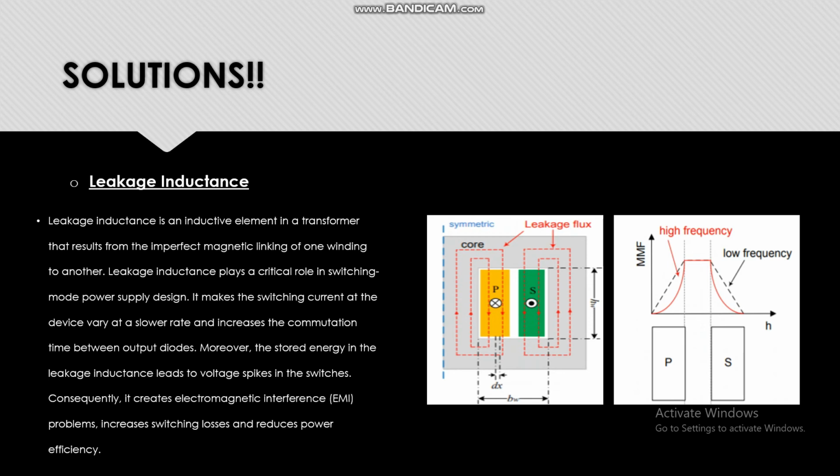To describe it more, I would say at higher frequency, the current will in general focus on the surface of the conductors and subsequently lessens the cross-sectional region of the conductors wherein the leakage energy is stored. This implies that the leakage inductance is diminished with increasing frequency.